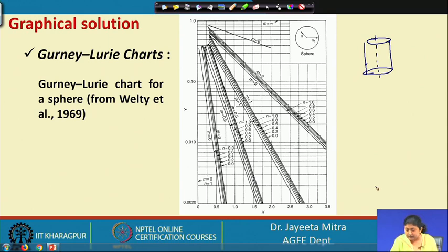So, in that case the parameter y that we actually need to consider will come as y plate into y cylinder, and then we relate this with the other Fourier's number and the dimensions m and n. So, there is a problem, and most of the cases in food samples when we go for preservation using sterilization,